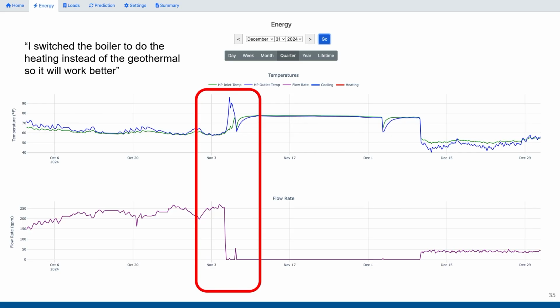And so I don't know how your contracts are written, but if you're offering a certain amount of guaranteed savings, you'd probably want to measure and verify that, but it can be costly. If you have a central plant, maybe a little bit less costly, but in a lot of cases, there's water to air heat pumps throughout the building, maybe in each suite. For a multifamily building, that is very much not cost effective. So look at that ground loop, understand if it is maximized in terms of its usage, then you're probably 80%, 90% of the way there.